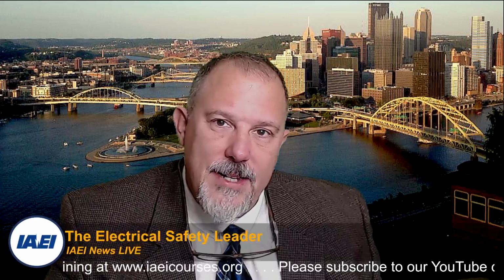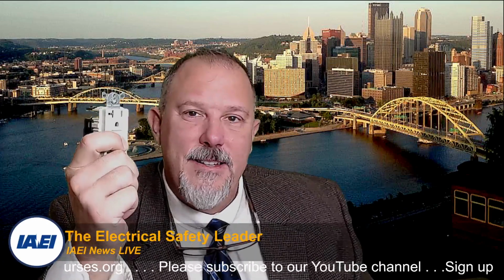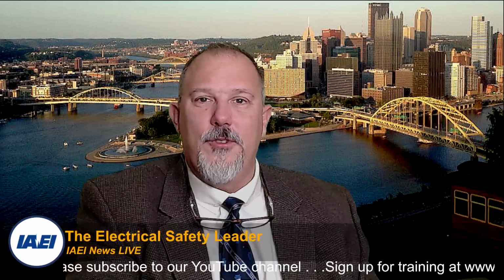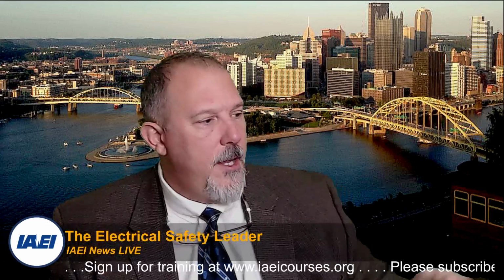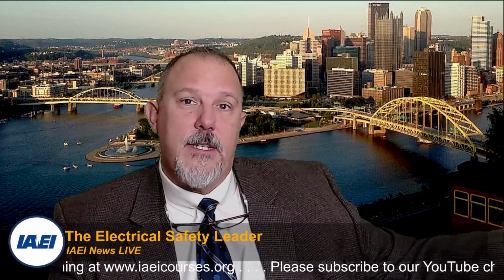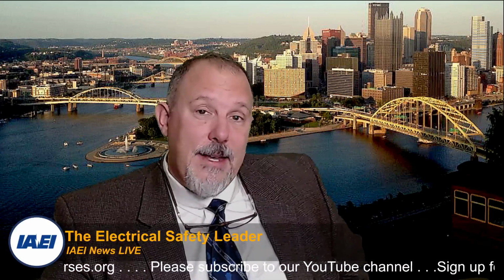What's a great way to test it? Press the test button. De-energize the circuit. Then go to your load, what's being supplied. Go right here to the face. You shouldn't power anything up. Get a lamp. Plug it into the face of this. It shouldn't power up. Anything that is supposed to be GFCI protected, plug that lamp into those receptacles. If it doesn't power up the light, it's not energized.